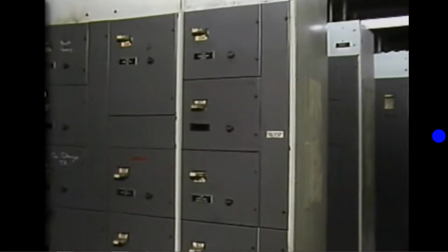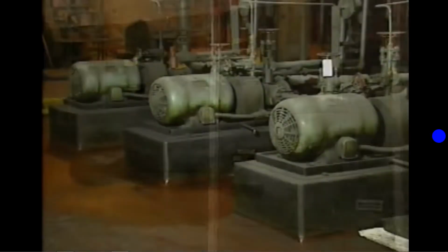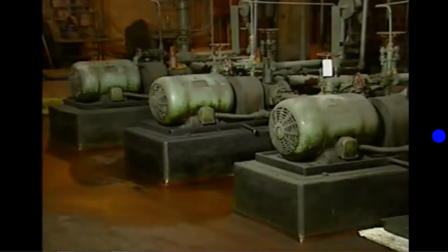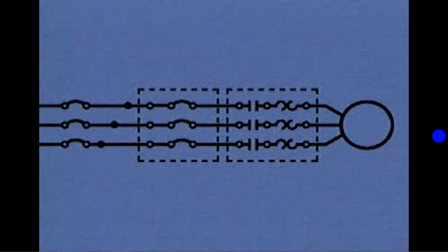Some magnetic motor controllers also provide low voltage protection. Insufficient voltage can result in motor damage. When the voltage a motor receives decreases, current increases, and the increased current could damage the motor and its windings. The last device represented on the diagram is the motor served by this motor branch.